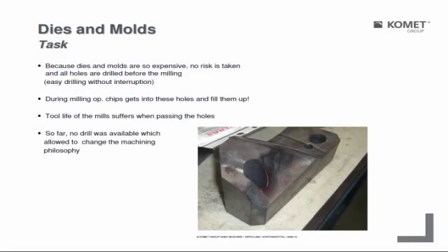This die and mold application. When you look at the component, my first idea when I saw it would be: let's drill the hole first and then do the milling operation. This is exactly what the owner of this component did. But he was facing the problem that these holes were filled up by the swarf of the milling process.